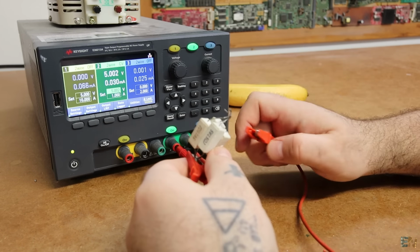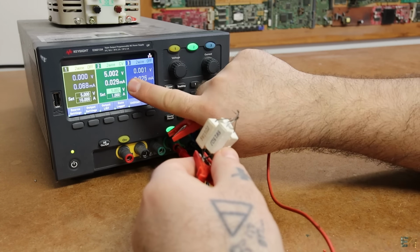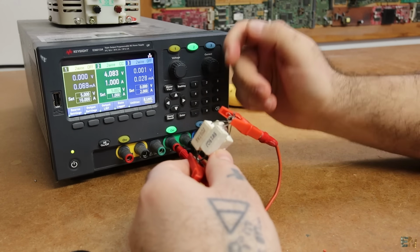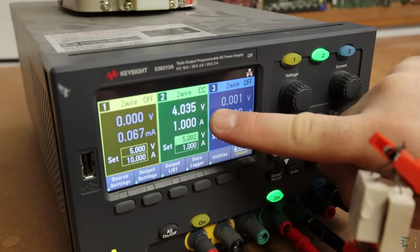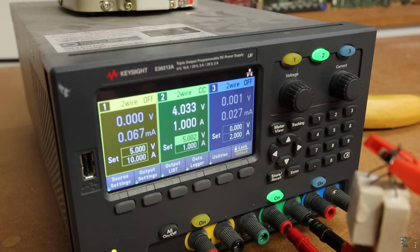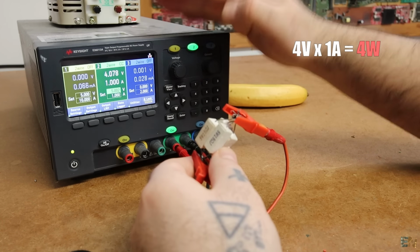So here I have my load, and now I'll connect the output. Pay attention to the voltage value, also to the current value, but more important, the voltage value. So I connect the output, and as you can see, the current is limited to 1 amp, but now the voltage instead of 5 volts just dropped to 4 volts. And that's the problem, because now the maximum output will be 4 volts multiplied by 1 amp, in this case 4 watts.